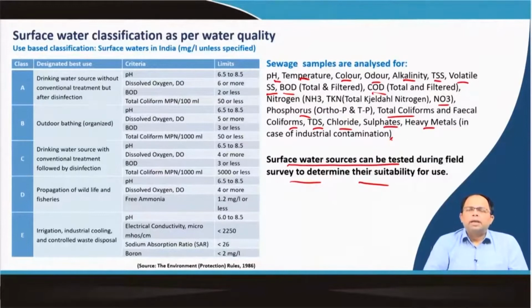So, you go to an urban area, survey the different water bodies or lakes, and give proposals: should there be projects to prevent sewage inlet into those water bodies, or a project so that there is some form of treatment before the water that overflows from the surrounding area goes into the water body, or should there be a drain around so that we can divert the runoff that goes into the water body, or is there a need for connecting multiple water bodies? All these things need to be tested.